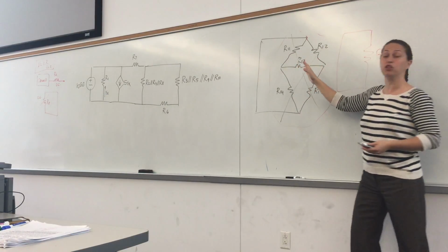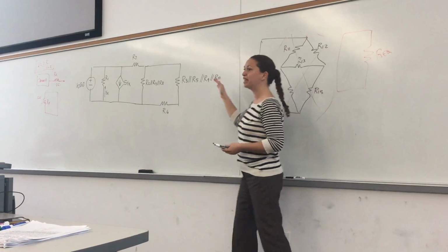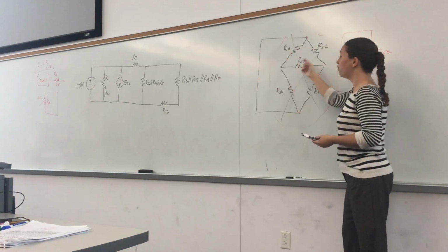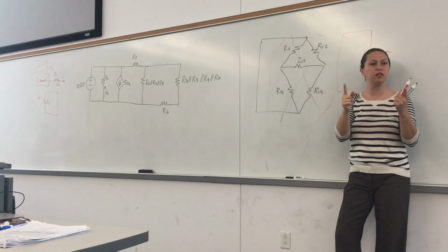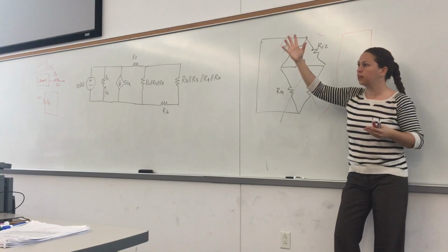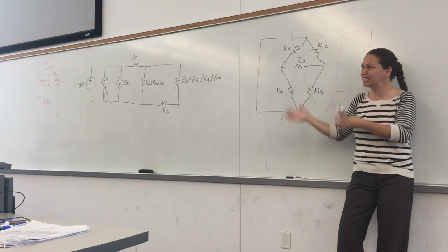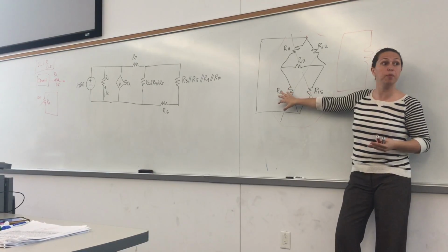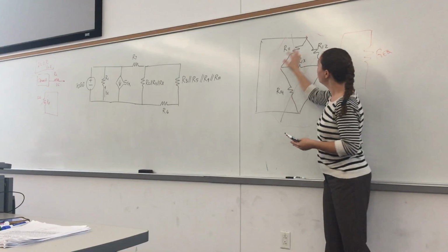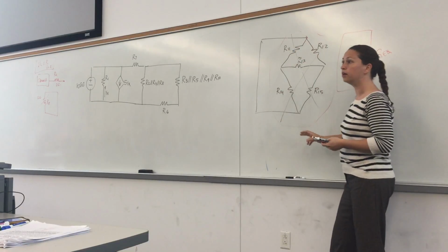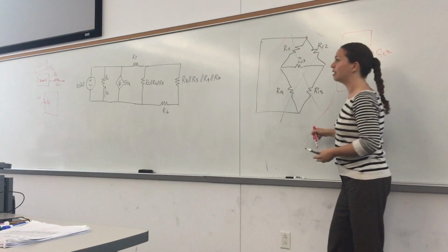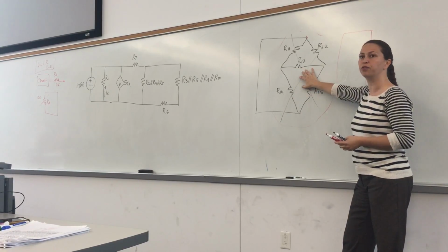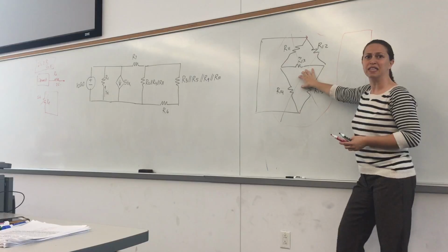It doesn't matter. You can just go along the way like we did last time, and then eventually see that that whole 5 resistors turn into a resistor, either floating or shorted, and then at that point could be ignored. Or you can look at the problem at the very beginning and say that this whole thing is in parallel with a wire, so I'm just ignoring this whole thing at the very beginning, and just in step 1, you can get rid of that. Is that clear?